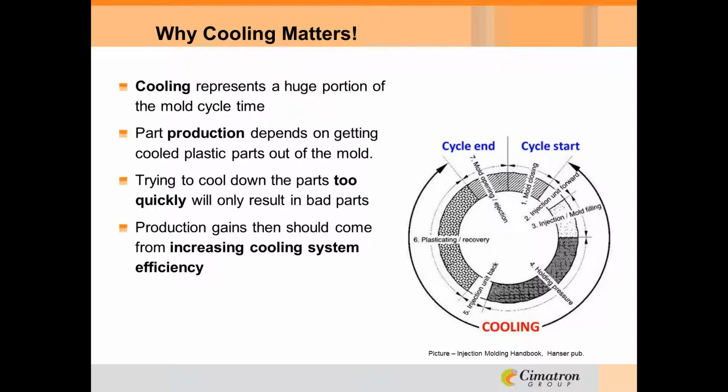Well, in injection molds, the importance of an efficient cooling system cannot be overemphasized. The water flowing through the mold is the primary means of removing the heat from the plastic part, and as the part cannot be ejected until it's cooled, this has a direct impact on the bottom line. In a diagram of cycle time, the overall time spent cooling the part makes up the largest portion. So it's not unusual to find that a 1 or 2 second reduction in cooling time can lead to a 10 or 20% increase in production.